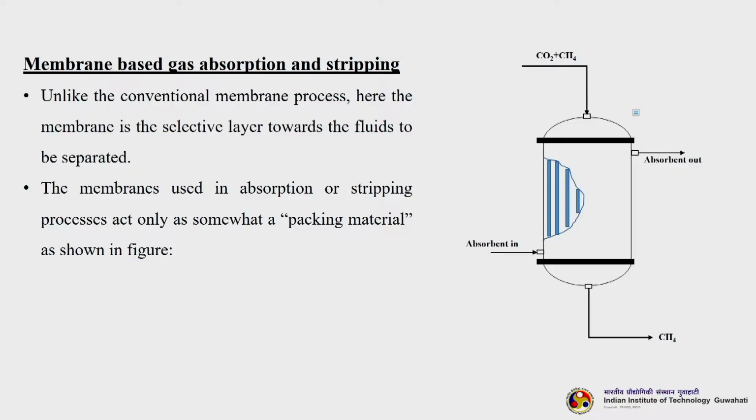So, another application, one extended application of gas absorption, is gas absorption and stripping. Unlike the conventional membrane process, here the membrane is not the selective barrier or selective layer towards the fluids to be separated. The membrane used in absorption or stripping processes acts only as a packing material, as shown in the figure. You can see that instead of having a packed bed for doing the absorption, we can have membranes packed as a packing material.